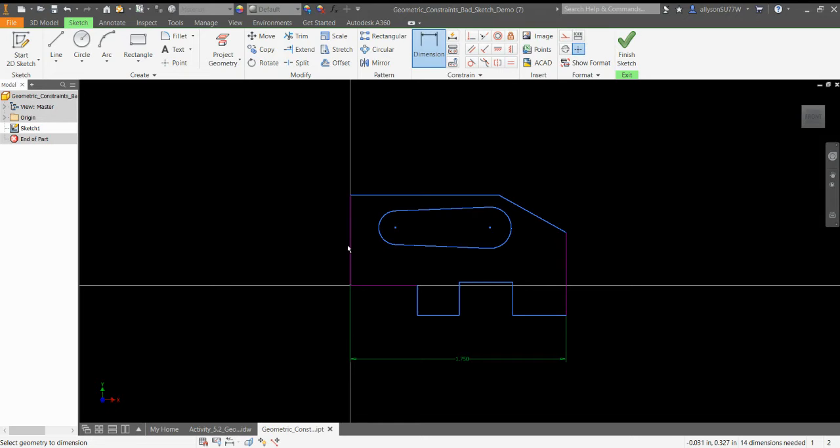I'm going to come over to this line, which is one of our other larger ones. And this line should be 0.85 inches. So we have two basic dimensions, and you can see that the shape of the profile is changing, but the things that we constrained, they all stayed the same. So now I want to look at some of my larger sections.